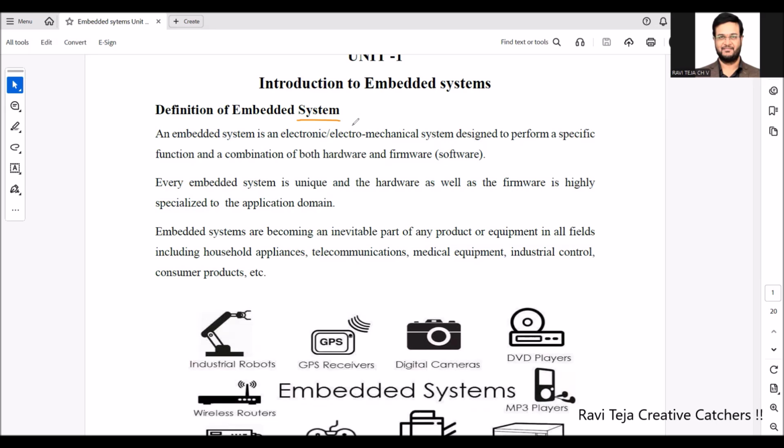If you are going for a microcontroller, inbuilt memory will already be there. If you are going for a microprocessor, you need to add some external memory, such that whatever program we write, whatever set of instructions we give, will be uploaded into the memory of that particular chip or computer, so that whenever we give some input, it gives the output automatically. So we are trying to embed a set of instructions or a program. To keep it simple, we are embedding software into the hardware.